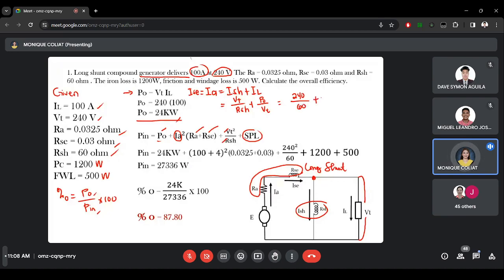27,336. Yes, very good. We have 1.12. So it is not kilowatt, okay. Because we can cancel our kilowatts here. So the factors in our power variables are unitless. That is why we have a 1.12 diversity factor. Our diversity factor is always greater than 1. Please make sure that we remember that. Since we already have 4 kilowatts above, we can cancel it.